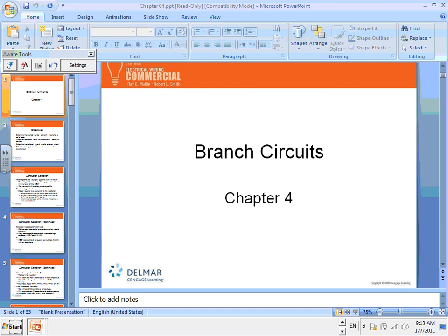If you use circuit 1 here and circuit 2, guess what? You already balanced it just by taking 1, 2, 3. You balance the lighting load right into phase A, phase B, phase C. Okay, so for the storage, they did the same thing.